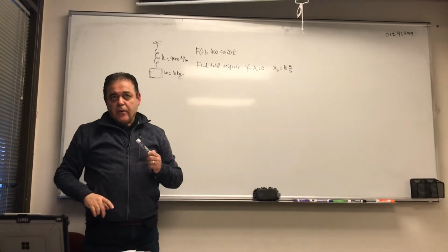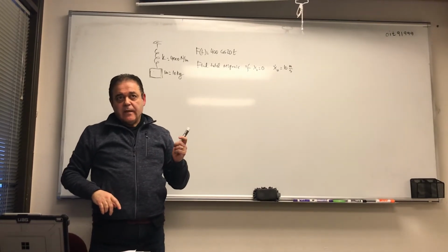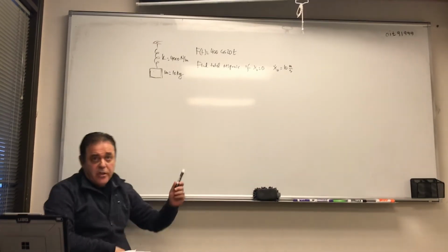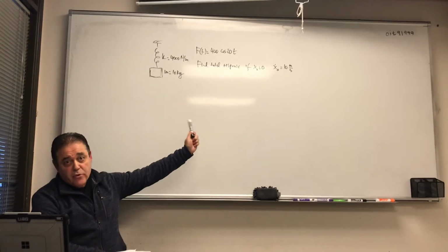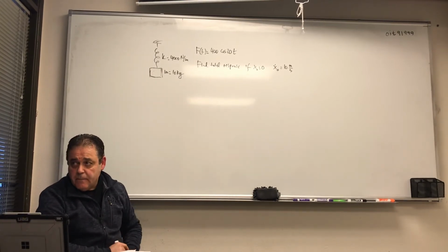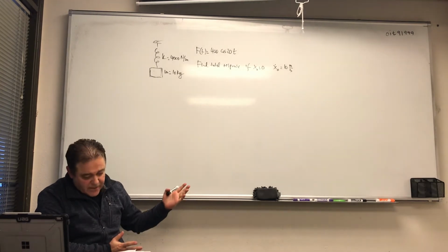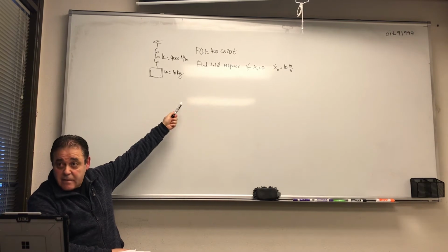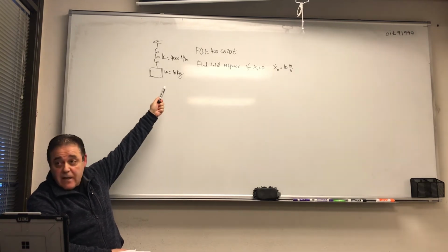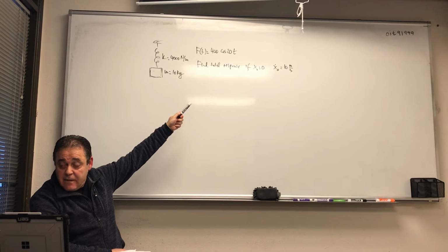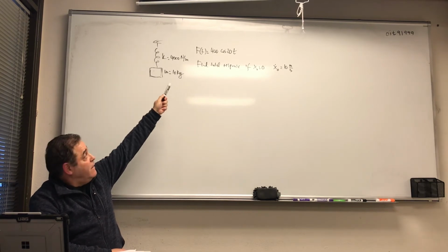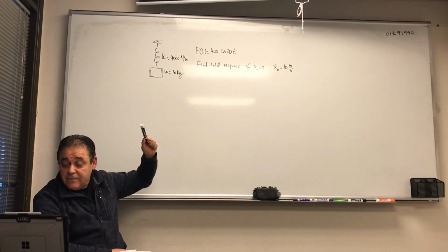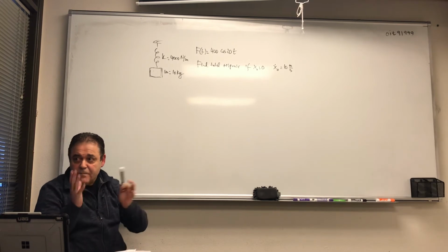Let me throw in a quick question here. If we want to write a differential equation that describes the motion of this mass, what would it be? Would it be mx double dot plus kx equals 400 cos 20t? Exactly. So it would be 10 x double dot plus 4,000 x equals 400 cosine 20t.